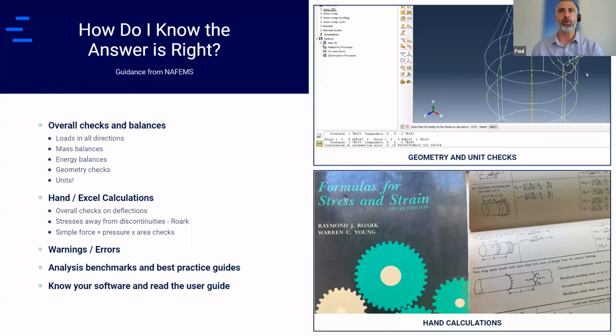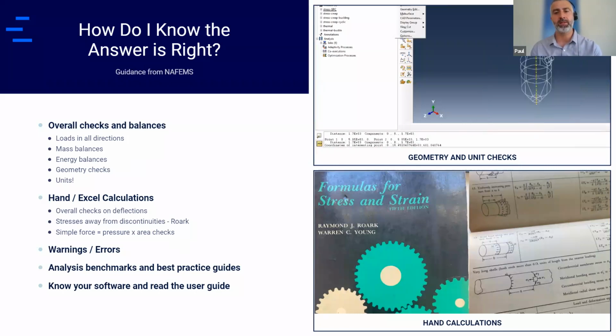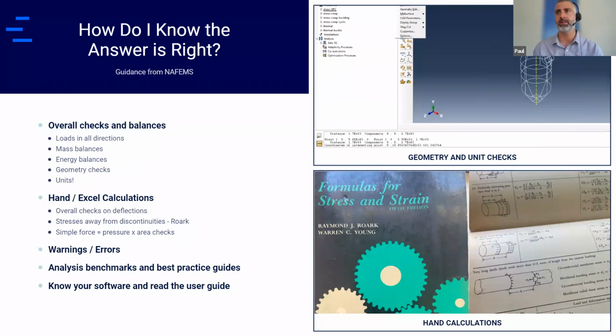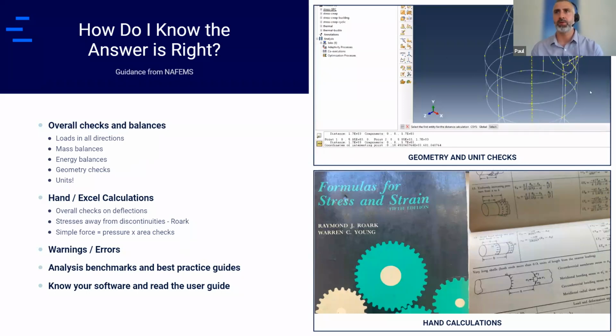So if you're lucky enough that your software, the CFD software that I use, for example, I don't really have to think about units at all, but in the FEA software I'm using, I do. So it means that you have to be very, very careful, because units is something that comes up all the time. And I just recently reviewed someone's hand calcs, and they'd done some stress analysis calcs and mixed meters and megapascals, and something was built that broke.